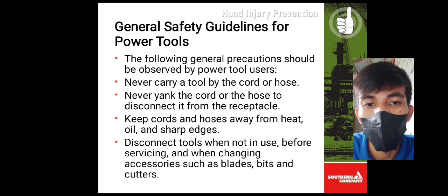Never yank the cord or the hose to disconnect it from the receptacle. Keep cords and hoses away from heat, oil, and sharp edges. Disconnect tools when not used, before servicing, and when changing accessories such as blades, bits, and cutters.